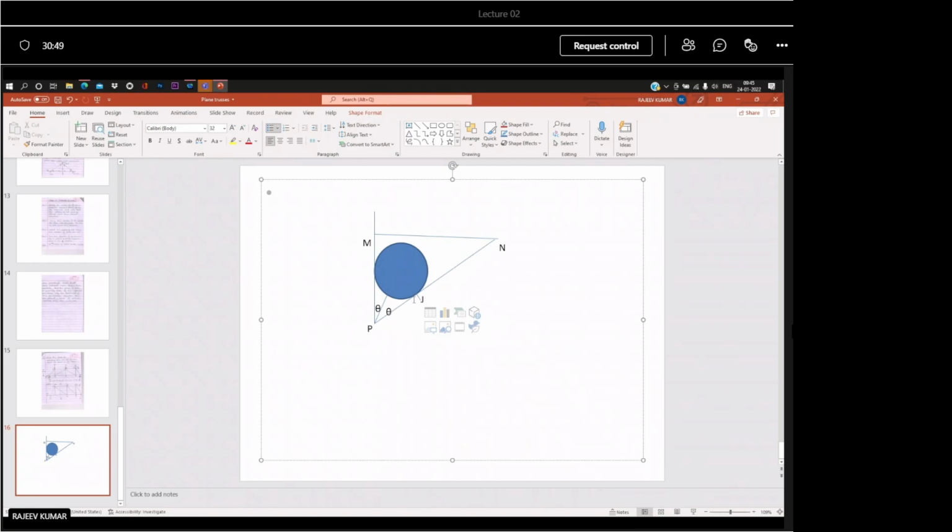So from center here and this, if you see, and also you draw a perpendicular here that you give the name Q. And this reaction will become Rj. So first you calculate Rj. So Rj sine 2 theta is equal to 600. If you will draw the free body diagram, this will come in this one way.